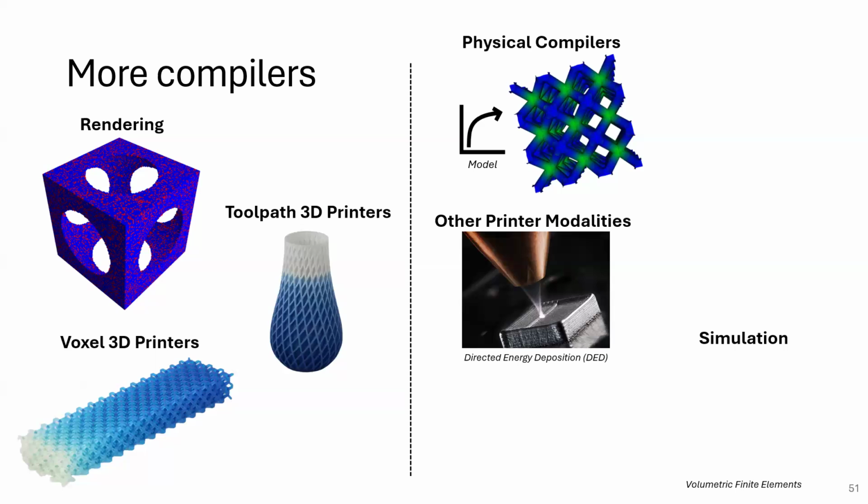Don't you also have all sorts of problems that, if you do that kind of energy, doesn't it heat up? Yes, there's all kinds of problems with that, isn't there? Yes, and one of the interesting things actually relates down to this bottom box: to do DED really well, you want to simulate how you're printing it, where that laser's hitting, to optimize for not moving the laser back to the area that might still be cooling, right?